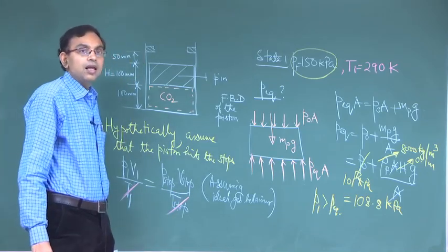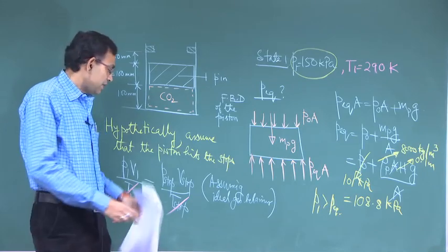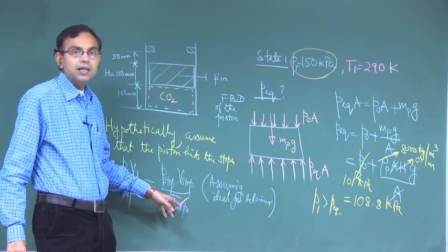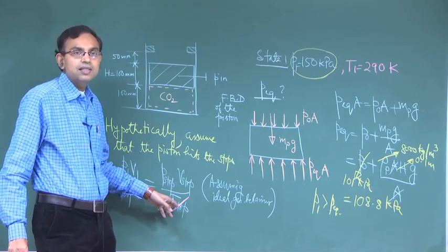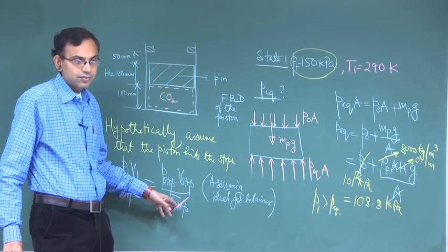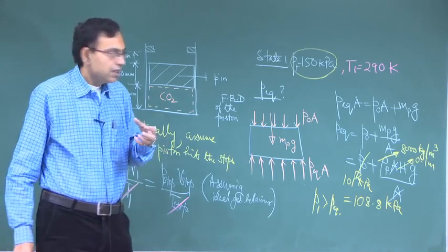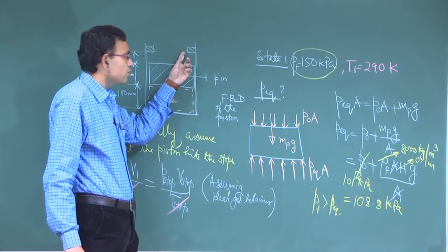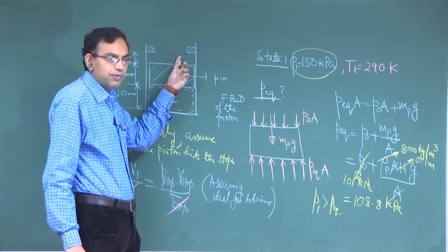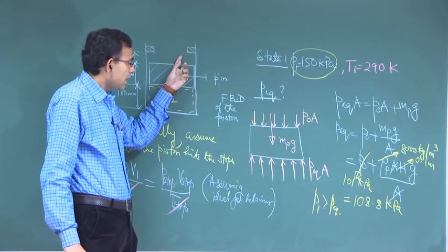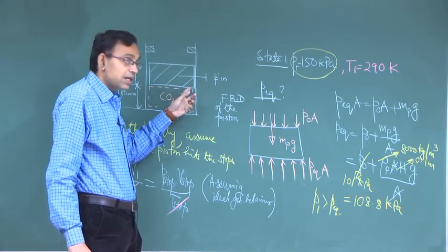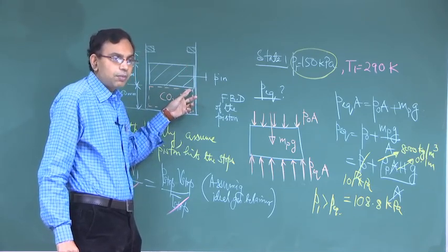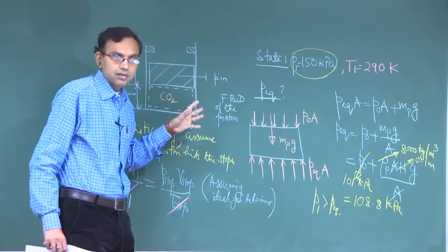Remember that T1 is equal to T stop, that does not mean that the process from 1 to stop is an isothermal process. It says that the piston goes to whatever, it may be stop or below the stop, and then the system is allowed to come to ambient temperature by maybe transferring heat.